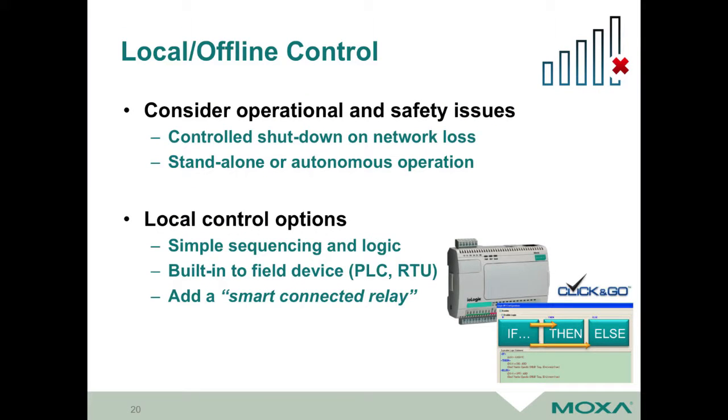And if you're not a PLC programmer, don't let these intimidate you. Some of these can be programmed off the front keypad with a display. Or with Windows-based programming software, and some are even just simple if-then-else style programming, where you can say, if this digital input turns on and 5 seconds have elapsed, then do this. So you don't have to be a rocket scientist to do some of this stuff.